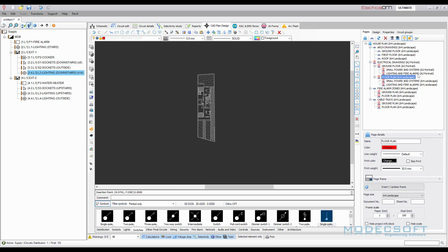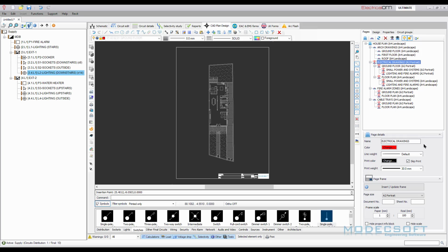I'm doing the same for the other. So I'm going to skip this from our print report because we haven't placed anything here. So we can select the layers we want to skip and select the skip print option. Okay. So also we don't want to see architectural drawings we included because we want to see them in the electrical diagrams. So now we managed to define the layers we included in the ground floor of this electrical diagram.